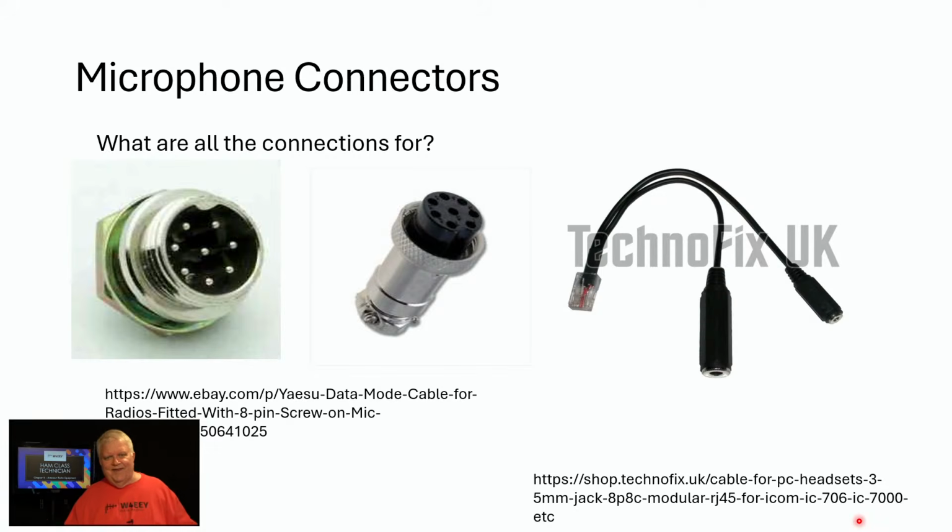here's a little heads up. The connector there on the left is called an 8-pin Foster connector. It's probably one of the more common connectors for medium older radios. Kenwood used it, ICOM used it, Yaesu used it, others used it as well. It was not standardized, so the pin layout is different between various manufacturers. So I caution you that if you got an ICOM radio and you've got a Yaesu microphone with the same connector, and you say, I'm going to plug it in there, it might not work.